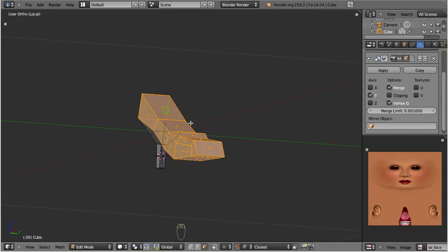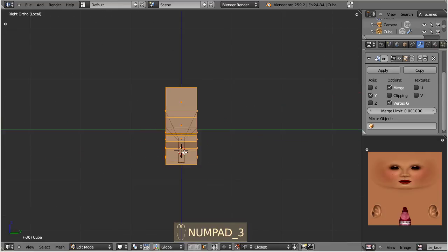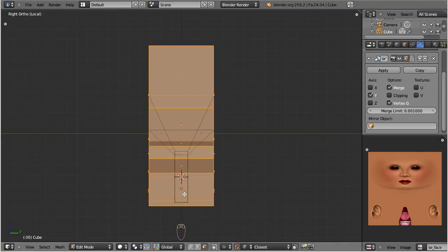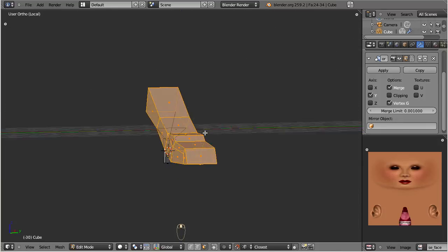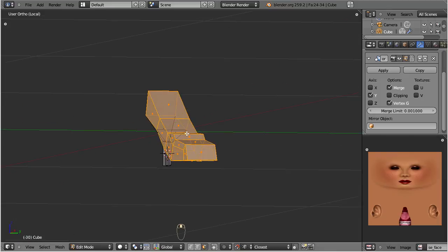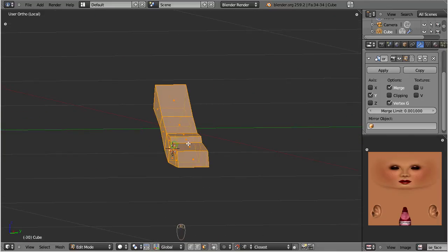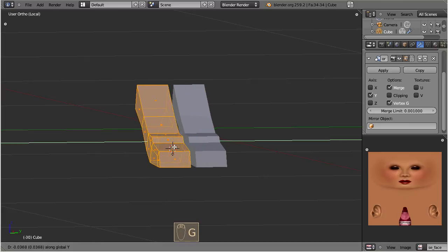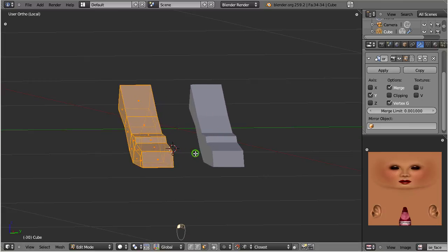Well, you must know that the mirror plane always goes straight through the object origin, and this currently is located at the object center, hence the modifier mirrors the object into itself. We only need to go to Edit Mode, and move all vertices to the side. You see that the mirrored part now moves away into the opposite direction.